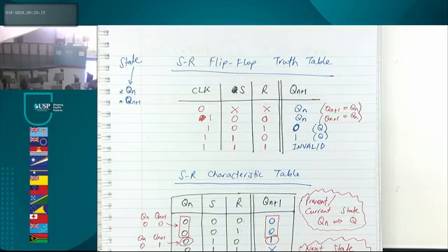What does that actually mean? That means, what happens in that 1-1 situation? Do you remember the word I used last week? Racing, yes, racing. The flip-flop starts to race. It starts to blink on and off at a very fast rate, right? Okay, and that burns our flip-flop. So it's basically on and off means it's storing 1, then storing 0, storing 1, then storing 0.